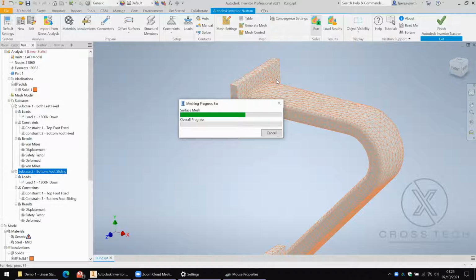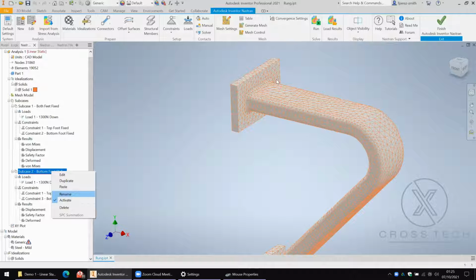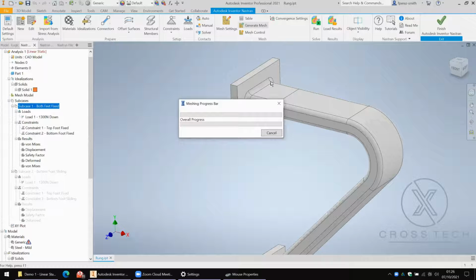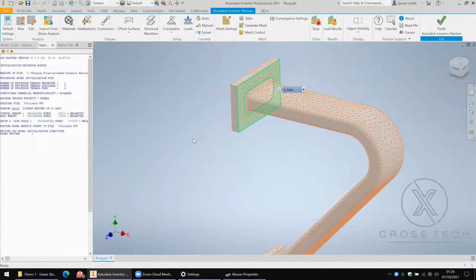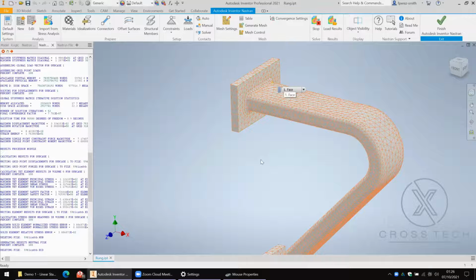So what it's doing is it's running the analysis, and then it's calculating the peak von Mises stress in it. And then what it's trying to do is refine the mesh in the areas of interest. So say, for example, it calculates peak stress here. It will try and apply a local refinement. And what we should see here on this convergence plot is a nice asymptote towards a static value. Now, if you are a bit ambitious like I am and you set your stop criteria to be 1%, it might not converge so quickly, but we'll see. Hopefully the demo ghost doesn't attack me today.